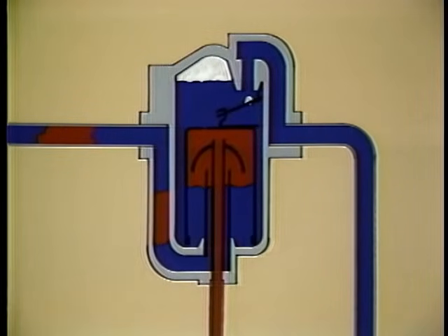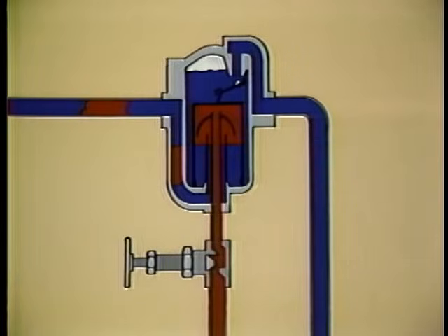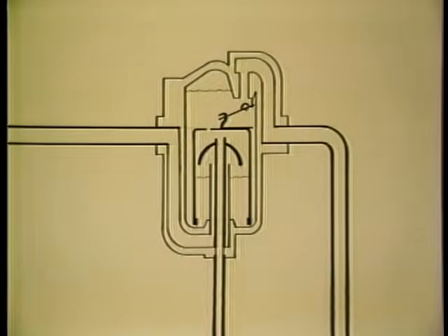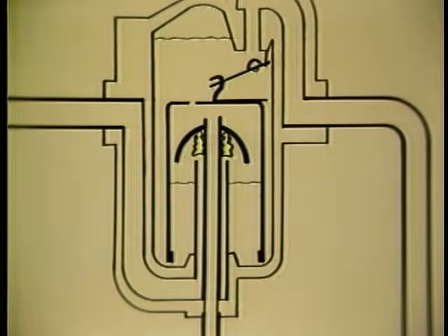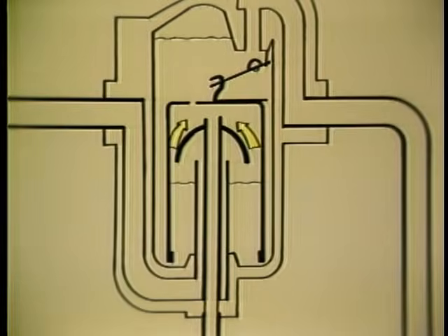The important difference is a secondary discharge tube which runs from the center of an umbrella-shaped shield coaxially through the inlet tube and is metered by a manual valve at its outlet. The incoming condensate and gases are prevented from directly entering this secondary discharge by the shield. The condensate forms a seal, trapping the gases inside the bucket, as with the IB. Steam, flash steam, and any non-condensables rise around the shield to the top of the bucket.